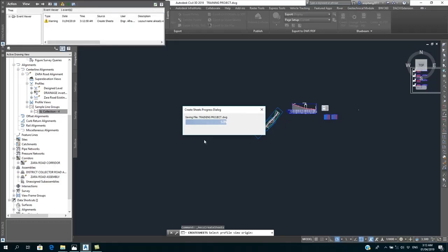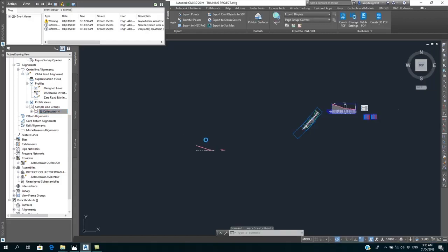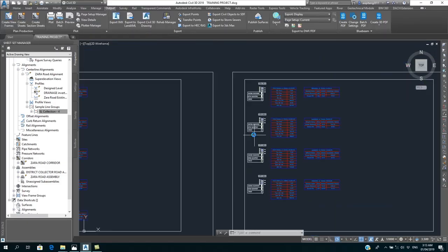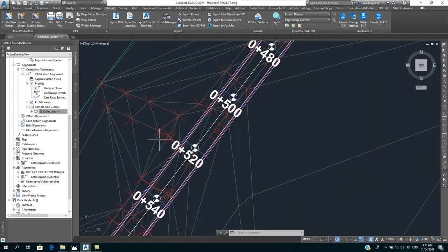So these are basically to explain the overview of using the basic tools in Civil 3D to arrive at a finished product in terms of the design levels, in terms of having your complete section view at intervals with the earthwork information details. So at this instance, if I want to review this work in Infraworks and get the information as details as built in Infraworks, all I need to do is to save my information as IMX from Civil 3D.